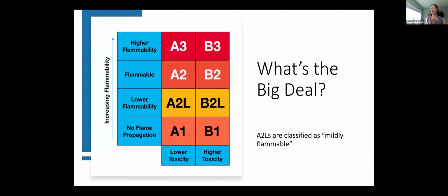The trouble here is that now that they are mildly flammable, if the concentration within the room meets a certain amount, called the lower flammability level, LFL, and there is an open flame in the room, there is a higher risk for that refrigerant to ignite. So with all of that, we are going to have additional life safety requirements that will impact construction and design.